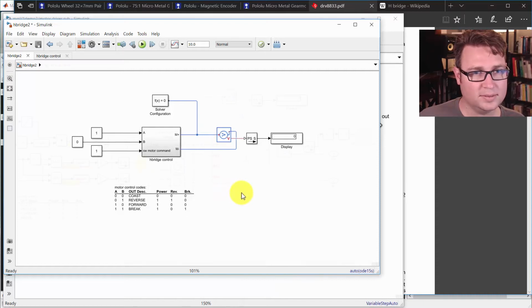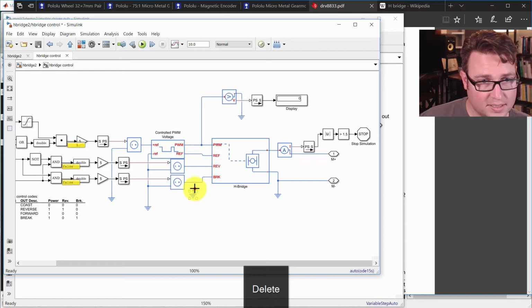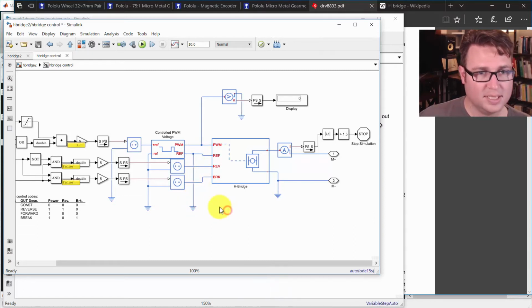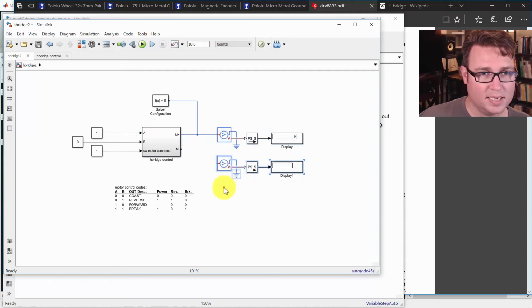Why on earth are you 0? That's connected to that. I have this connected to the wrong reference. That always gets me on this block. Ground was connected to PWM instead of to reference, so everything we do is going to come out as 0. So this should give us a 6, and lo and behold it does. Goodness gracious. Okay, so now let's make a copy of this